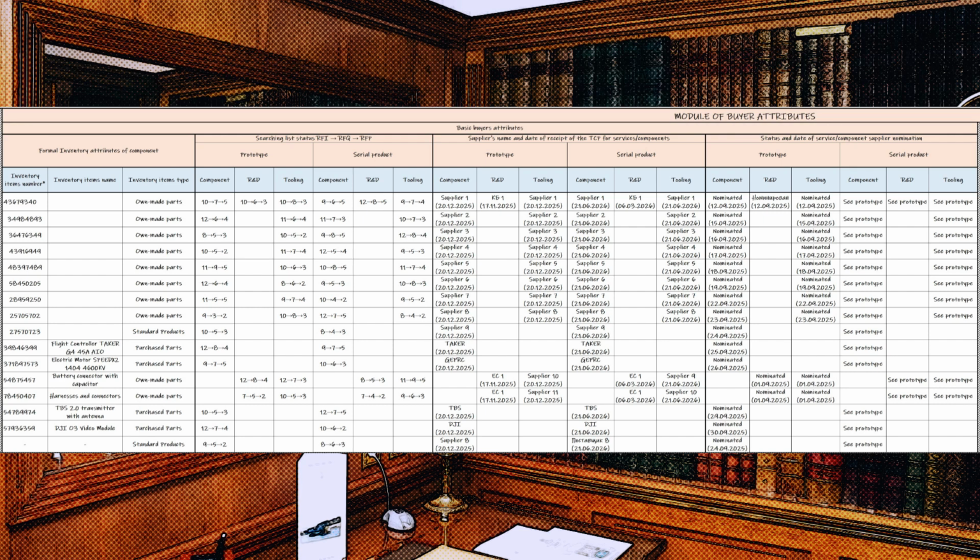Accordingly, in the case of filling in the BOM at the serial design engineering documentation stage, filling in the inventory item number column in most cases is firstly automated, and secondly it's highly desirable. The inventory item number is assigned in the internal accounting system of the procurement service in accordance with the business process in force in the company, which doesn't relate to the scope of our review. For a cost engineer or project manager, the inventory item number may be needed for a local task, but in general it's present in the BOM with the status for reference.